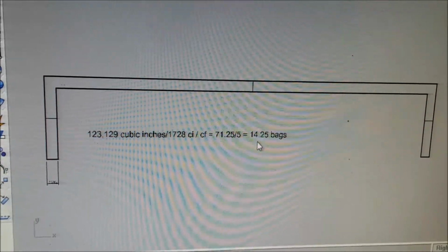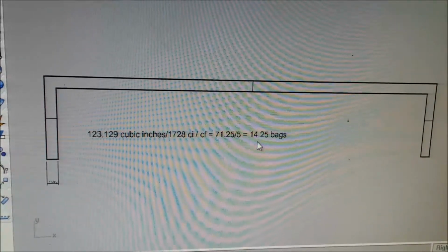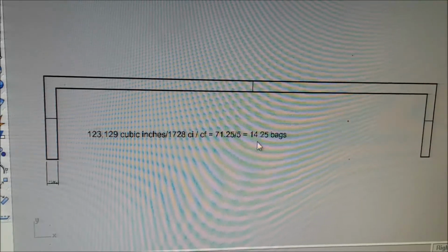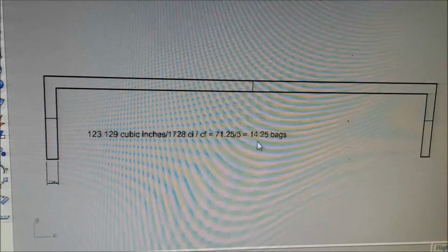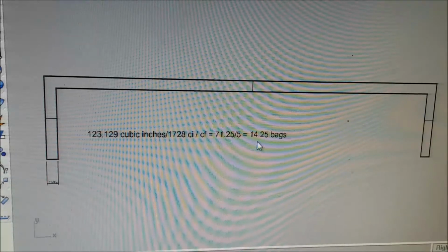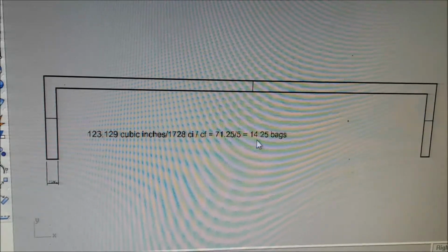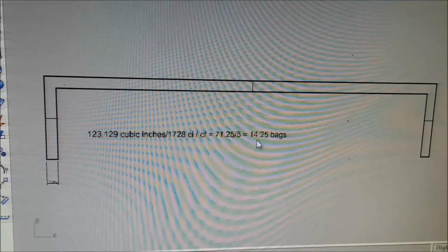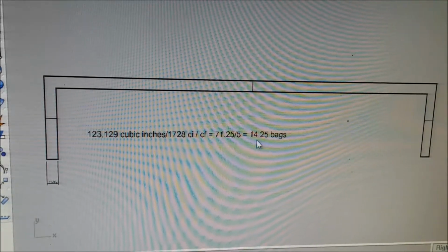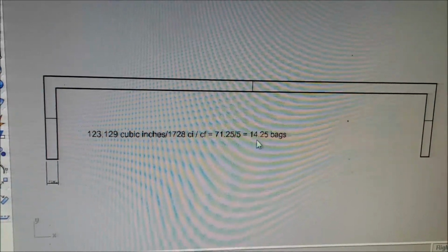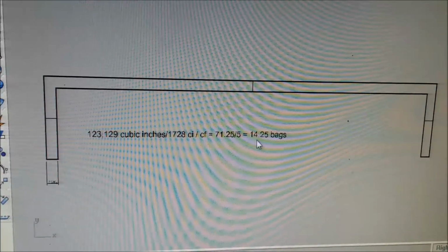And all these numbers, we always have, when we're filling our bags, we're going to fill an extra 6 to 10 bags on a pour this size, and expect to find them still sitting on the ground when we pour it. And we can just pick those 6 or 7 bags up and carry them to the next place we're going to run the mixer.